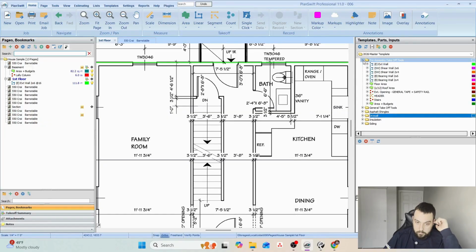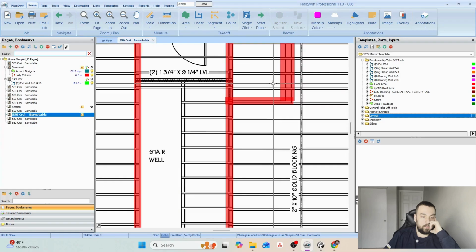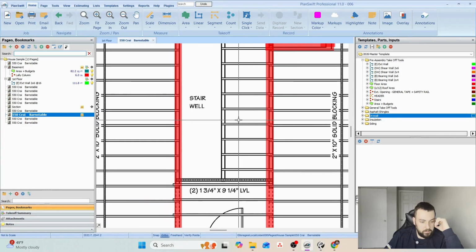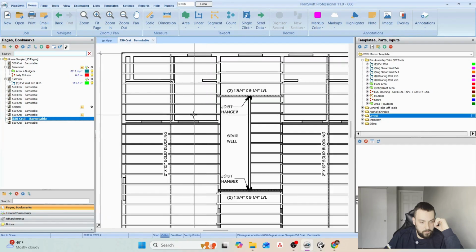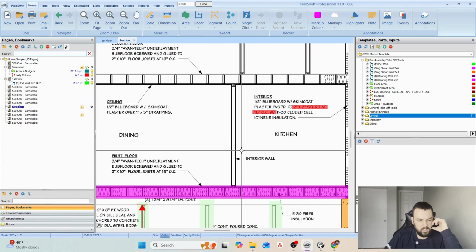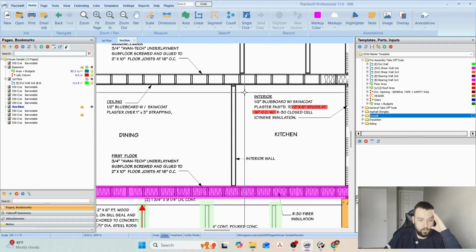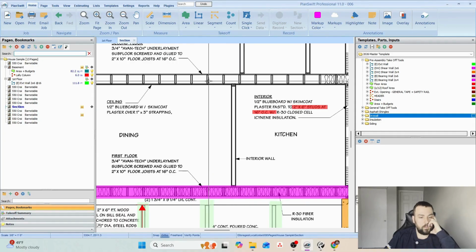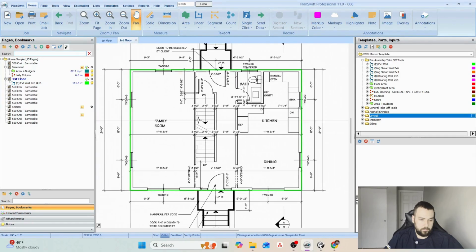Now I have to figure out, is it a shear wall or a bearing wall? It's not indicating any type of sheeting, so I think we can go without sheeting. It doesn't say anything. Small house, probably there's no need for interior shear walls, just exterior. And we can make sure our proposal excludes interior shear walls, just to cover our pricing.